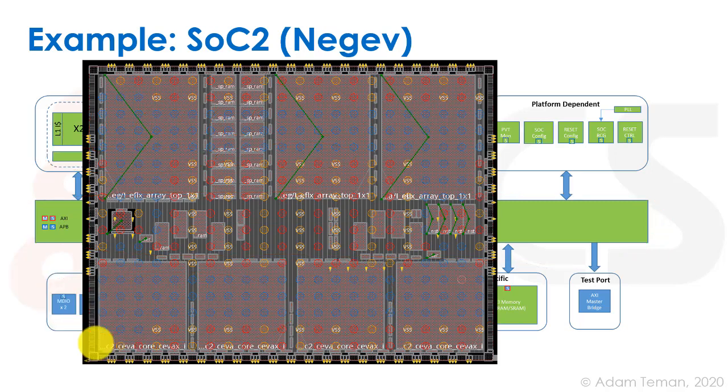Okay, this was then laid out in different CAD tools that we'll learn in future lectures. And you see that we have this physical structure, which has around the sides these IOs that I was discussing. And they're pretty big relative to transistors, because there may be many millions of transistors inside the chip, and there are only a few hundred or even fewer of these IOs. These little round things are called bumps. That's how we connected the package, and these are different blocks.